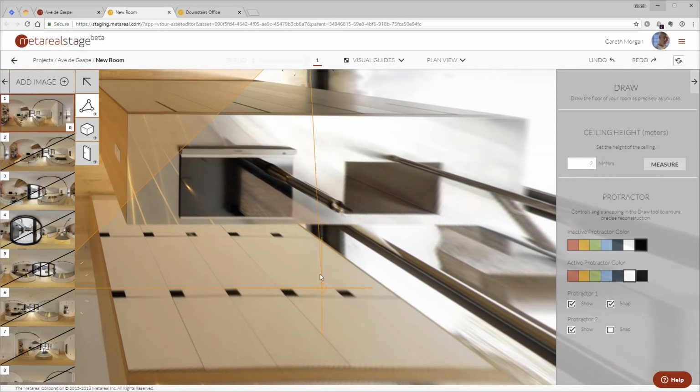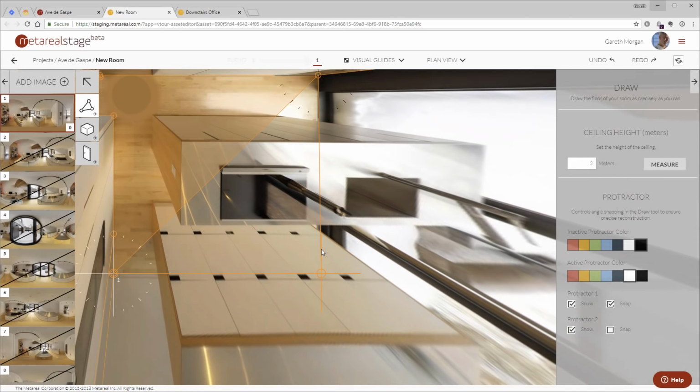Now over in this corner, we can't actually see where the corner is, but we have our 2 points, so I switch on my second snap, and the snaps will find the corner for us, so it makes it quite quick and easy to do.